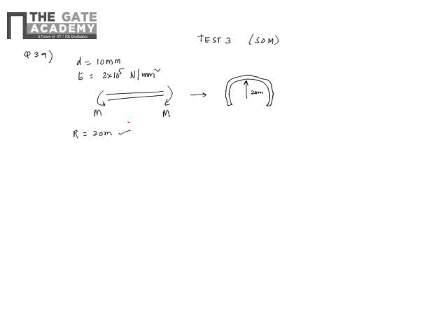Now one of the assumptions we have to make here is that though this is a large strain problem, the behavior of any material is elastic only up to very small strains. Once your strain increases to more than 0.2 percent, which is typically the yield strain, after that it's all plasticity. So we assume that the behavior is elastic. That's the only thing you can assume, because plastic behavior we don't study at the BTech level. So that's the valid assumption.